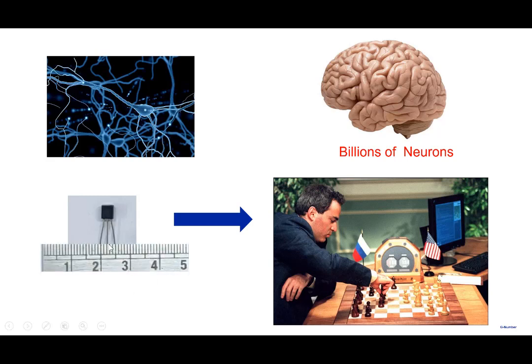We said the transistor measures, for simplicity, about 1/2 centimeter by 1/2 centimeter. This shows a layout of a circuit. We have one transistor here, another here, another here, and another here. Each transistor measures 1/2 centimeter by 1/2 centimeter, and between two transistors you have to leave some space for interconnection, so let's say the distance is also 1/2 centimeter. Then each transistor occupies an area of 1 centimeter by 1 centimeter.